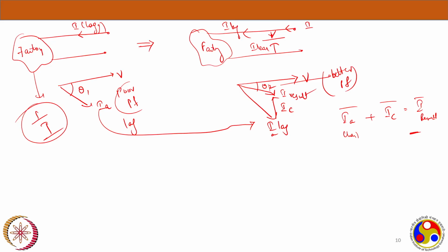So every time you need to connect and disconnect the capacitor bank based on the load requirement. People find this very difficult, because connecting and removing the capacitor on the bus system every time is neither advisable nor an easy process. So what people are doing now is, instead of connecting this capacitor, they are connecting a synchronous motor, right?